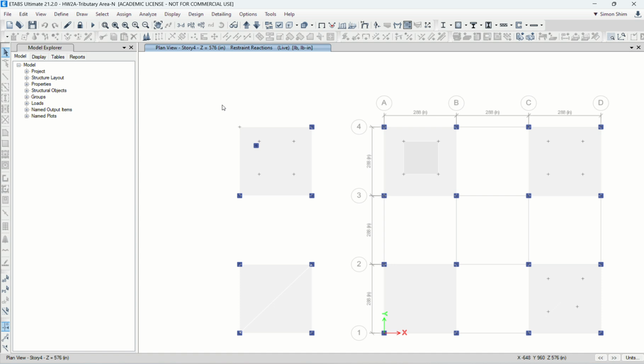Probably you can use center line approximation loading, approximation line, and then calculate the approximate trapezoid area. So like this, you could draw some influence line. When you draw it, you could just use the middle span, and somehow approximate the tributary area.